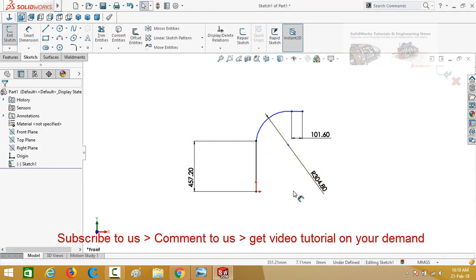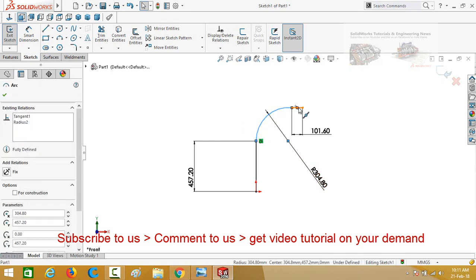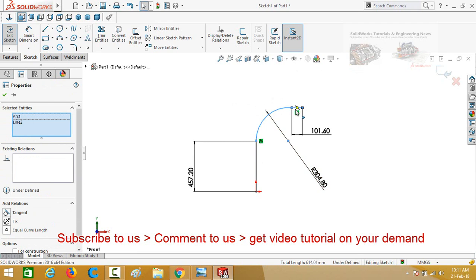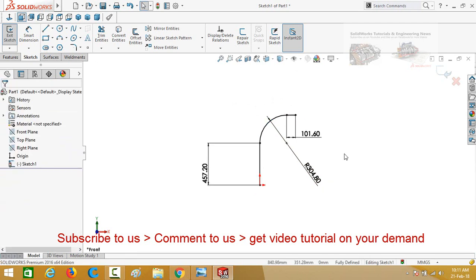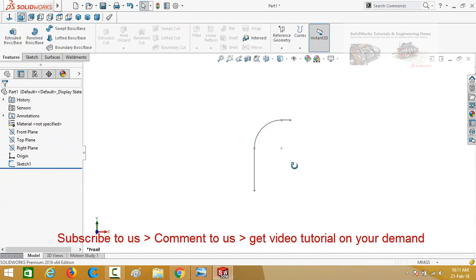Press escape button and then press and hold control key from your keyboard. Select this line and this arc. Make their relation tangent. Similarly for both of these arc and line, the relation is tangent. Our sketch is now fully defined. Press this button to save and exit from sketch.